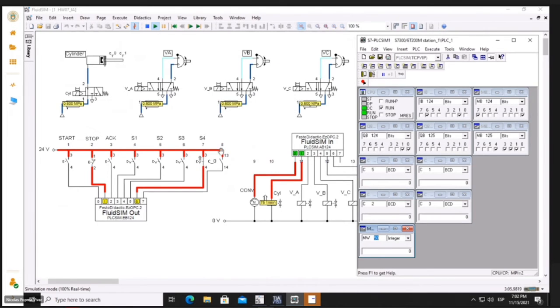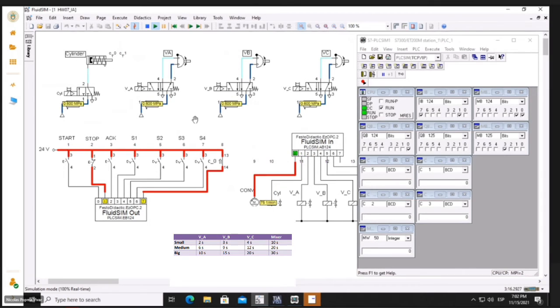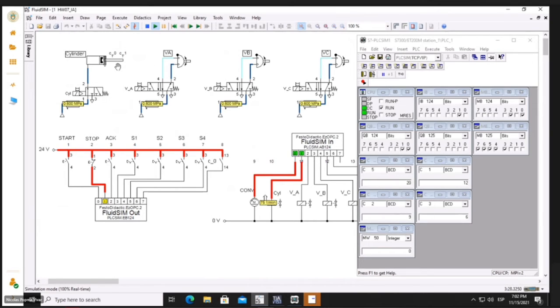And so finally, after the paint can has been mixed, we remove S4, which means that the paint can has left the conveyor belt and the cylinder will retract. And this means that a new paint can is ready to be processed. So now, by processing a medium paint can, we load its values, as you can see, 6, 9, 12, 20, and the cylinder closes again, and by pressing S4, the entire process starts once again.